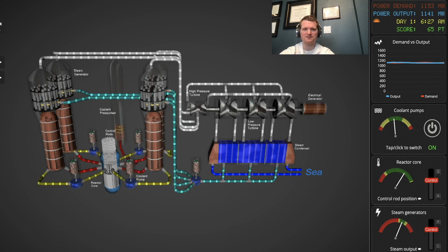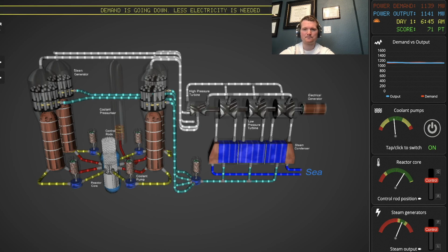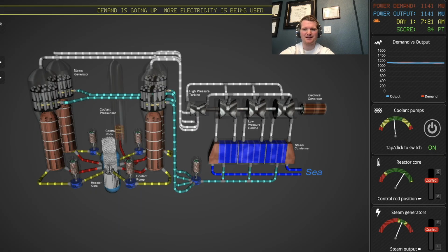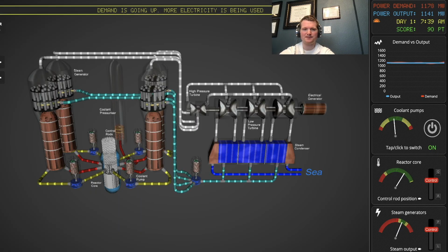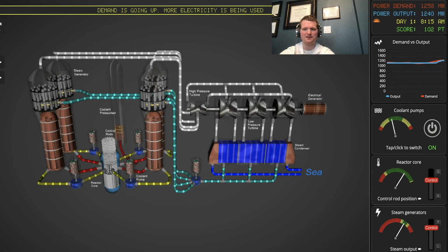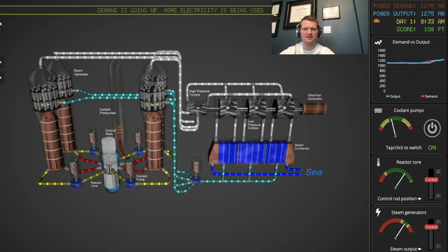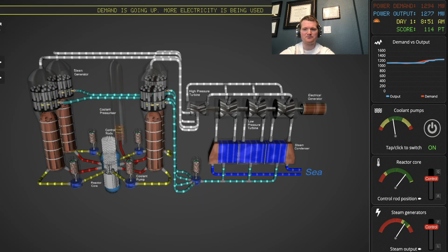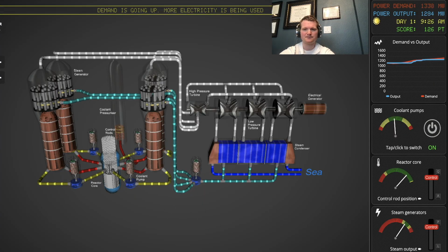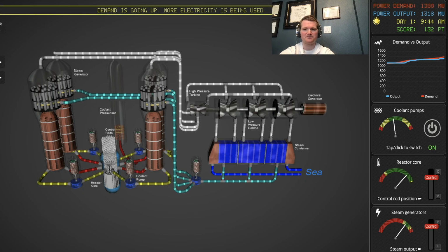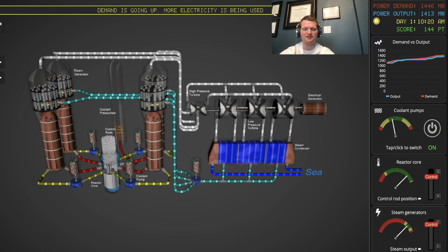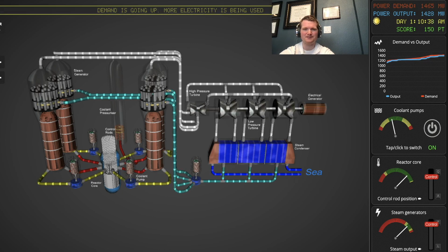It's fairly stable, fairly slow. What's interesting is reactor coolant flow actually stays about the same. I think they might be using it as an analogy for overall steam flow and feed flow, because that's mainly what you look at when you look at steam demand. Reactor coolant flow stays about the same more or less. So I think they're looking at steam generator flow and feed water flow is what this is kind of acting synonymous for. So that's a bit weird.